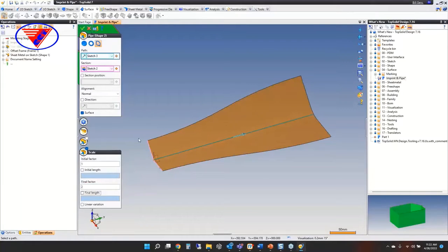Right now, it is doing non-linear variation. If I activate this, now it's doing linear variation. So you can see it's a straight line transition from the 1 to 1 scale to the 2 to 1 scale. Just depends on how you want to end this. If you're doing non-linear, what I want you to picture is there's a line perpendicular here, and this is coming off tangently there. Same thing down here, tangently coming off here. And same thing up here.